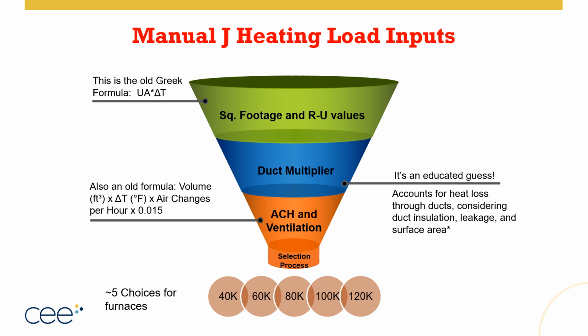With duct multipliers, there are some hardcore formulas, but most of the time we're making an educated guess, right? Because this duct multiplier is taking into account heat loss through the ducts, considering the insulation, the leakage, and the surface area.